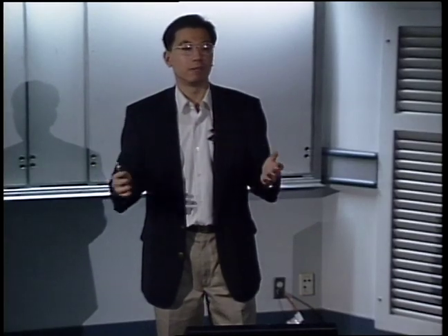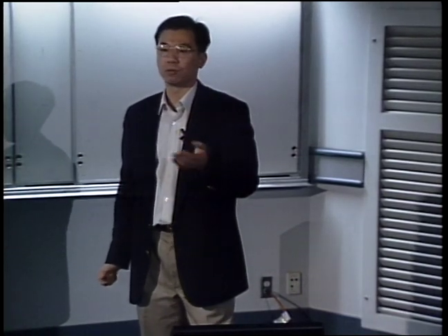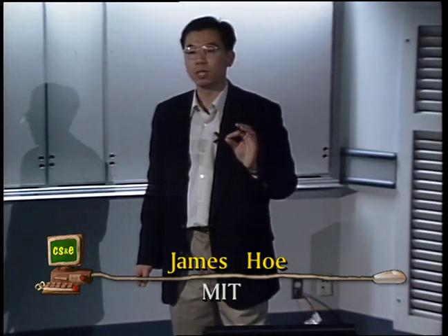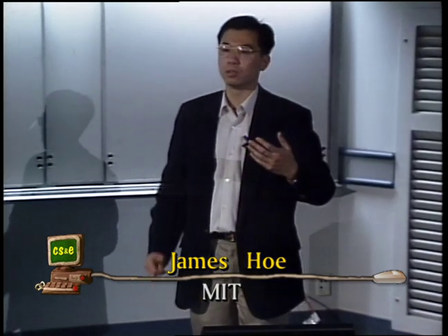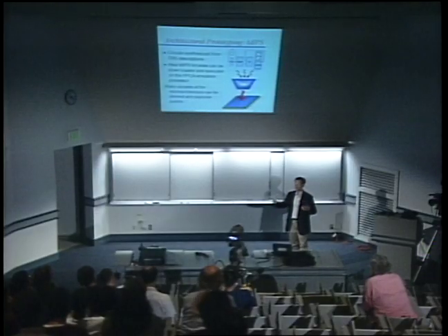We're still doing decomposition into operations. I think one misconception a lot of people have is that there's some magic in this. There is no magic in this. If you want to implement a processor with branch prediction, with speculation, you have to describe those mechanisms in my language. The compiler only knows how to synthesize what you have described. It's not going to suddenly invent mechanisms to fill things in. I have a description of a superscalar processor with branch prediction and speculation, and it's really the same fundamental issues. The new issues you get into are engineering issues. You now have a larger design, you have to break things into modules, and you do more modular design methodology.